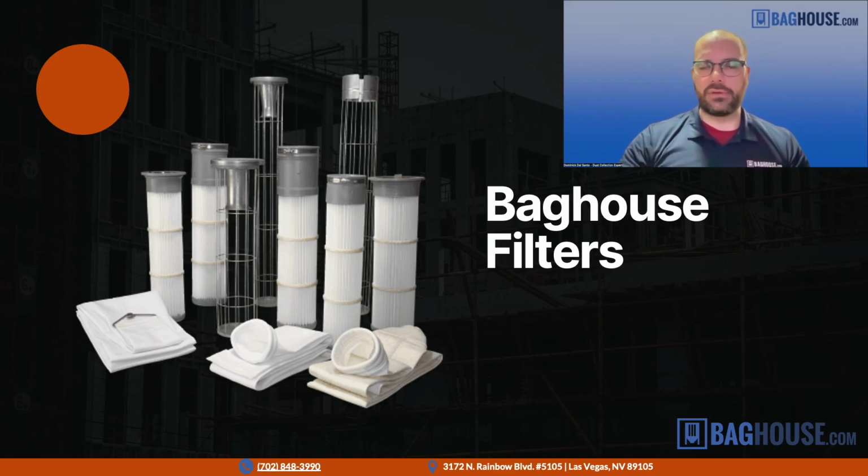And it's not just a spray coating, which unfortunately we've seen some manufacturers start promoting the same way. PTFE membrane is a separate filter material that's made and then laminated to the surface of the filter bags. And it has the effect of capturing more of the smaller particles and allowing for the dust to release more easily. So these are just a few of the common filter medias you'll see in the baghouses.